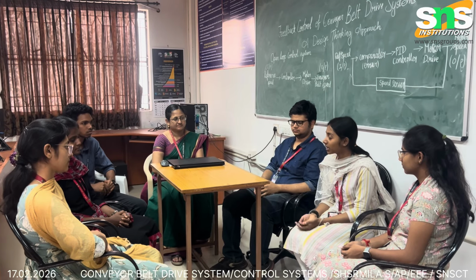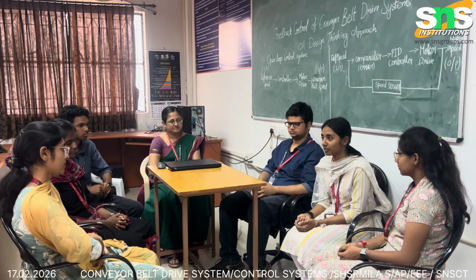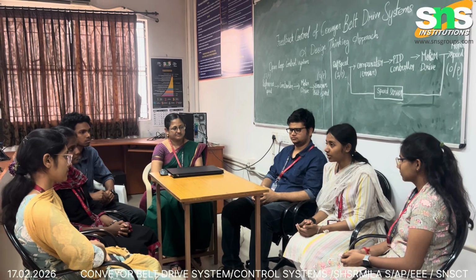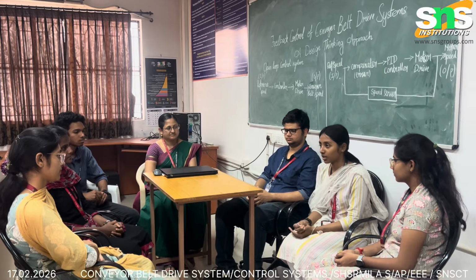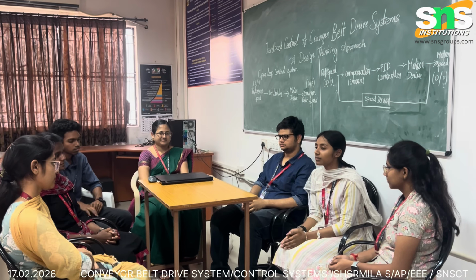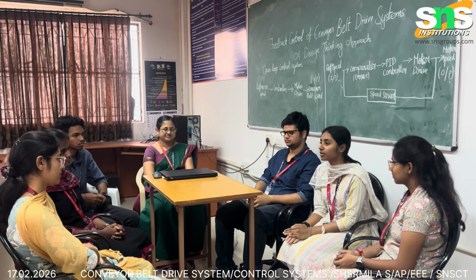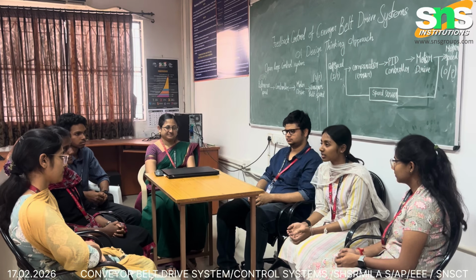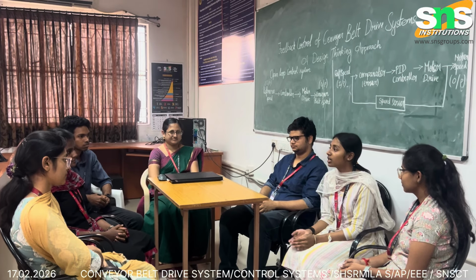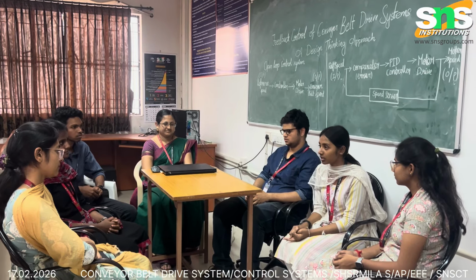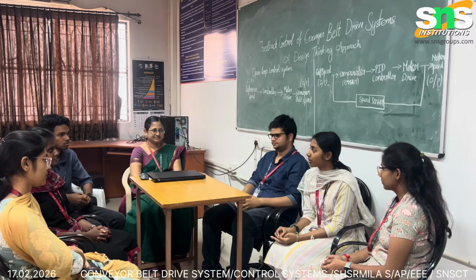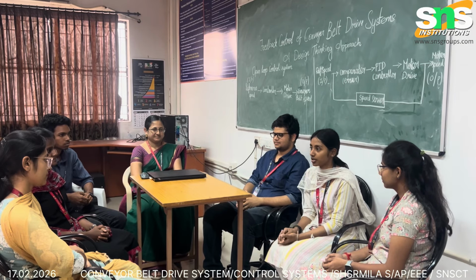Thus we came up with a smarter way, the closed loop system, our second approach. In the closed loop system, we measure the actual value using a sensor to achieve the required value. If the motor speed increases, the system decreases the input. Where the speed of the motor decreases, the system increases the input. This is what happens in a closed loop system. To build this system, we need a reference input, a speed sensor which acts as feedback, a PID controller, a comparator, and the motor drive.